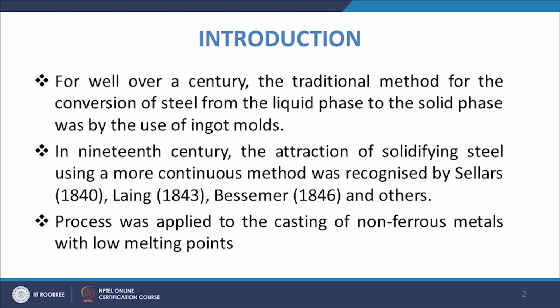They devised some means to do the solidification of steel in a continuous method, and initially the process was applied to the casting of non-ferrous metals with low melting points, for obvious reasons, like the higher temperature and the conductivity issues in case of ferrous materials. So, initially it was limited to the non-ferrous materials, especially lighter ones.